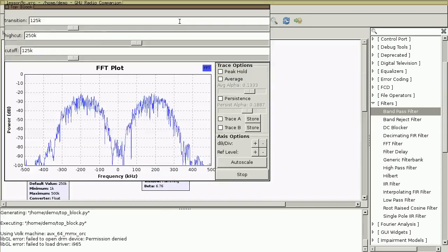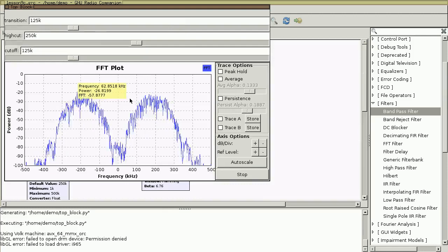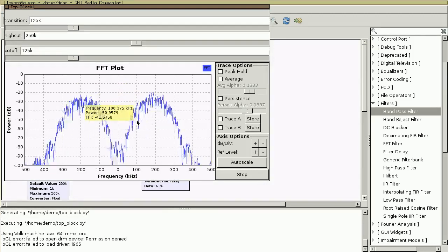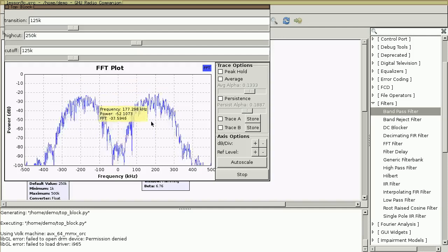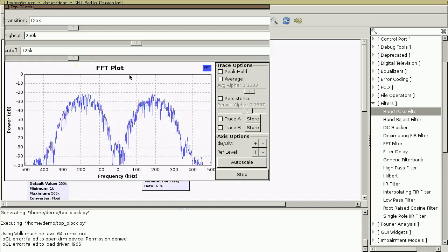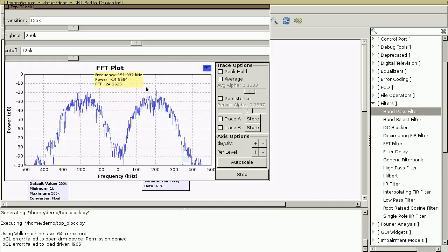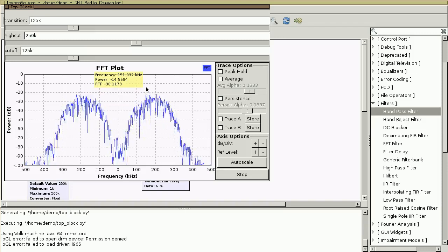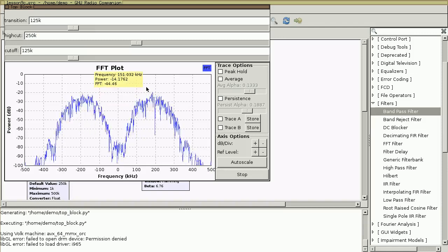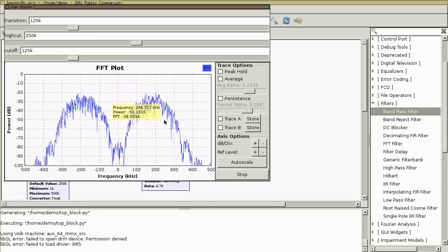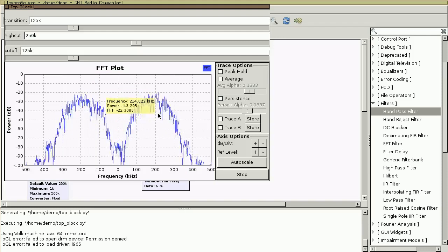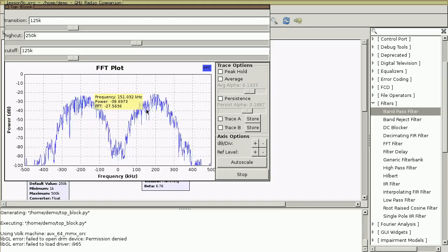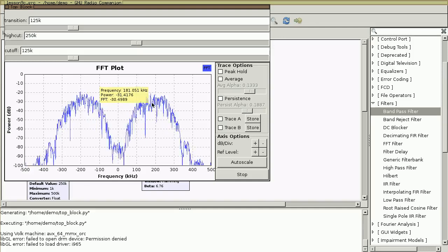Here we go. Now, this is my bandpass filter, and you might have imagined things as being just one band, but you can see we actually have two bands, some positive frequencies and some negative frequencies. And this is a consequence of having complex valued signals. So this particular filter might not be very useful, because most likely your signals of interest are going to be all together, not in two separate frequency bands. So if your signals are all together in one, it would be nice to be able to specify a single band that you want instead of what we have here, which is mirror image bands.